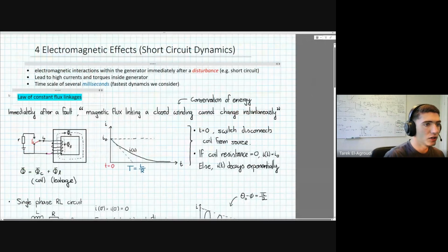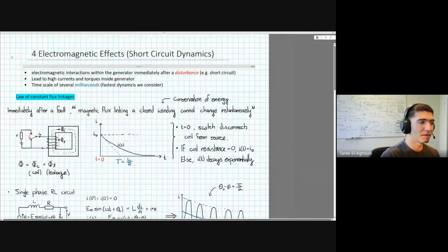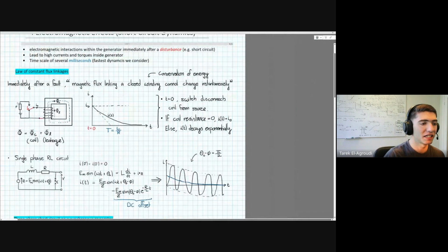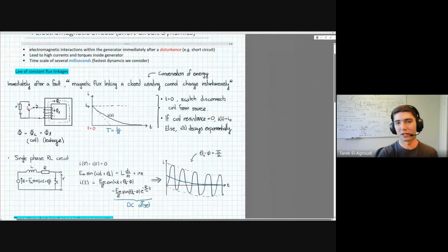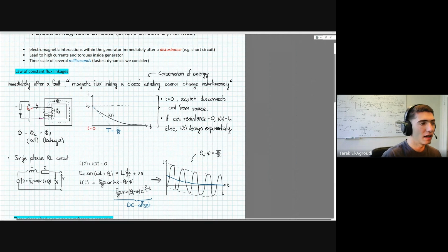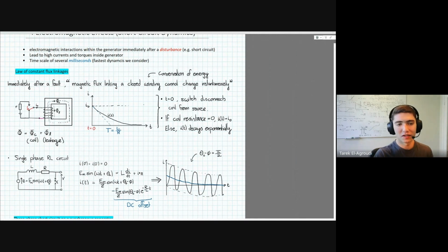During transients, what basically happens is there is a sudden change in the current, typically a short circuit or something like that, in the current and voltage which the circuit sees. And due to the principle of conservation of energy, if there was a flux going through some coil before, then currents will be induced in the coil, depending on its reactance, in order to dampen out these changes.